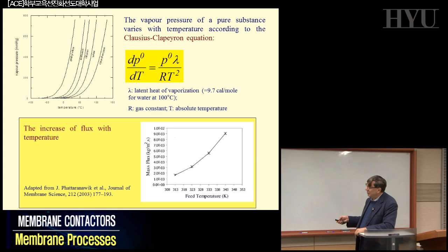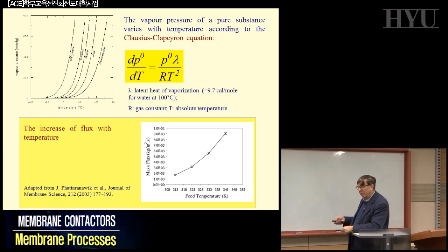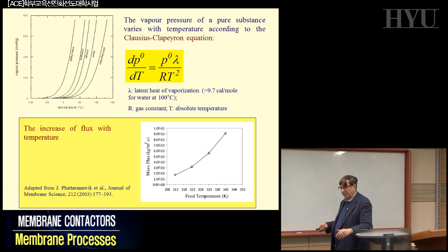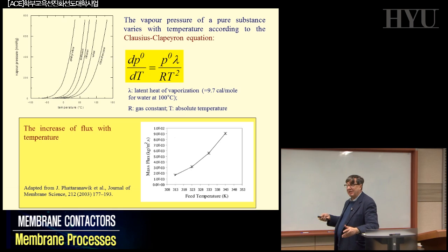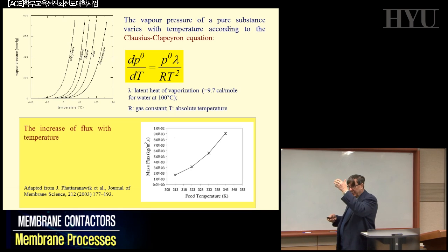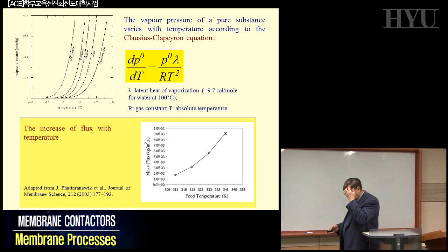But it's not this temperature that you have to create to move the molecules. The delta T across the membrane can be a few degrees centigrade, 10 degrees centigrade. That is enough because the membranes are basically very porous. Most of the volume is open. Porosity of this membrane can be 70, 80, 85% empty. So there is no mass resistance to the vapor going across the system.